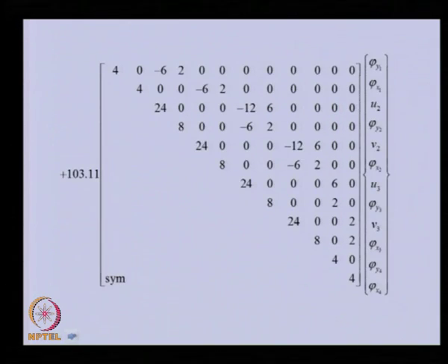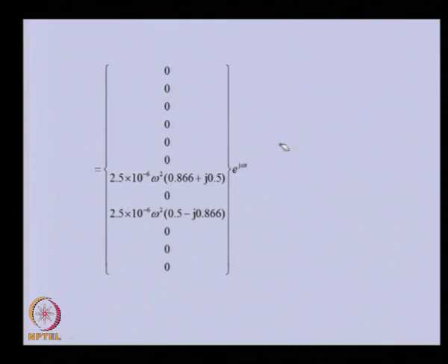So, this is the reduced form of the stiffness matrix, and reaction unknowns we need to eliminate. Only the terms containing the unbalanced force will be there in the right hand side, but other reaction forces and moments, if they are appearing, like at node 1 and 4, shear force will be 0. So, corresponding rows and columns we have eliminated. So, only known unbalanced forces are here.